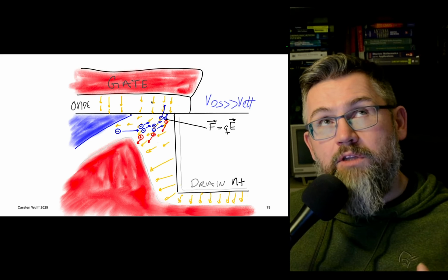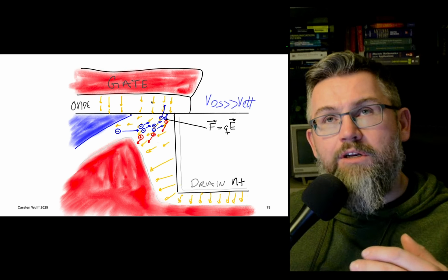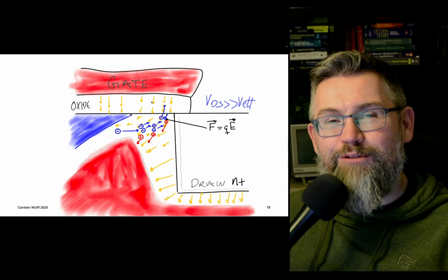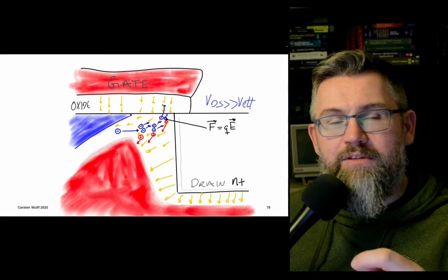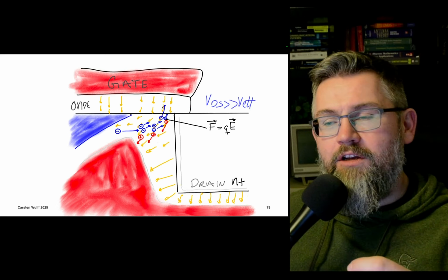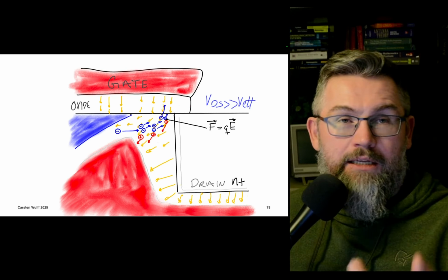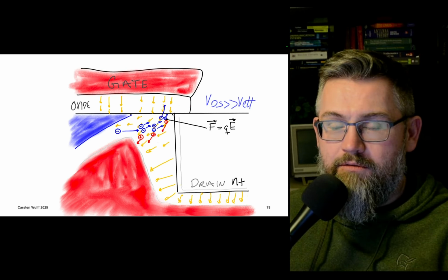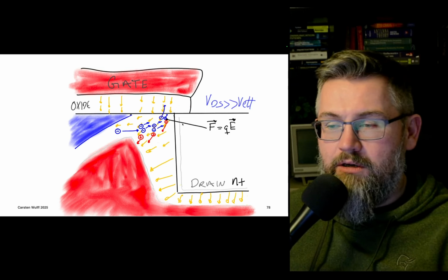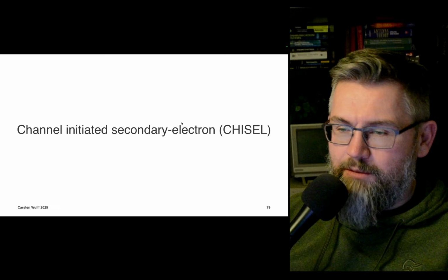and that can over time increase the threshold voltage. So you have to increase the gate voltage to compensate for the stuck charges in the gate. And eventually you might also damage the gate oxide. Or worst case, that's a different condition; we'll talk about that next time.